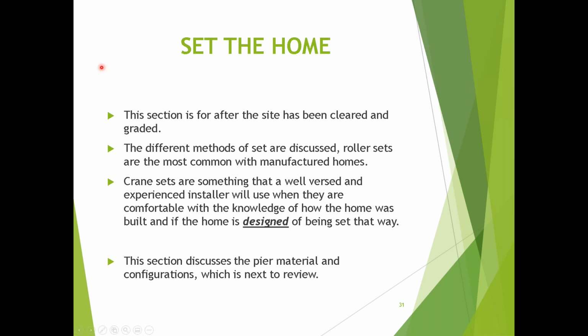When you get ready to set the home after the site's been cleared, graded, and prepared, there are different methods to do that. Roller sets are the most common for manufactured homes. Crane sets are something that most installation manuals say are allowed, but you really have to have the knowledge and you have to be comfortable with how the homes are built and if the home is even designed to be set by crane. In most cases, it takes a little bit more than what manufacturers provide.